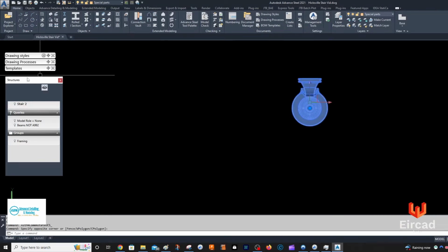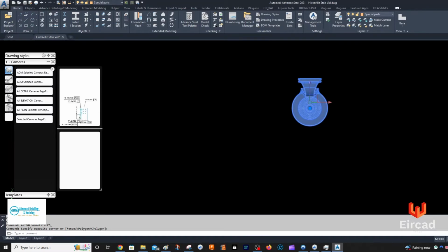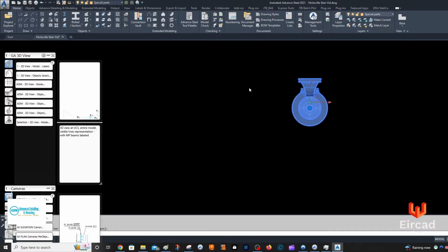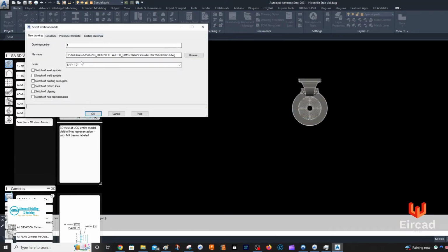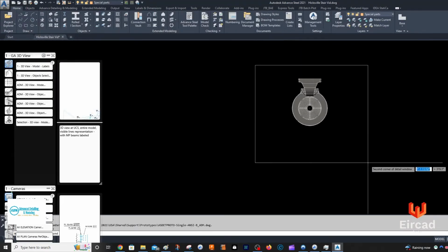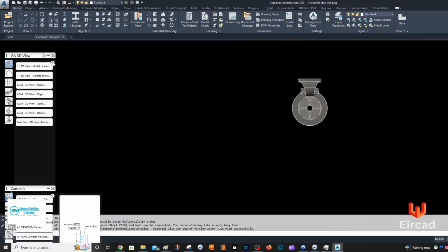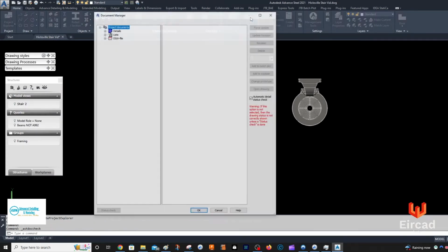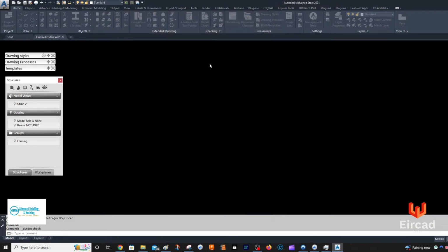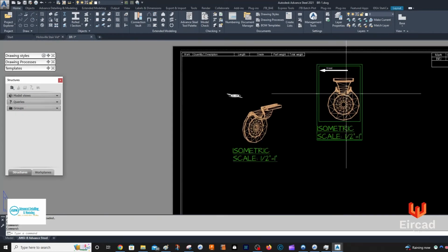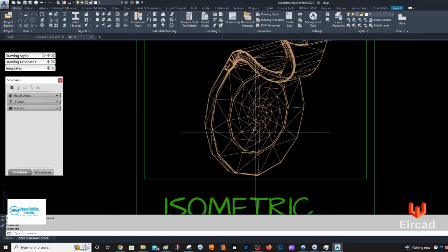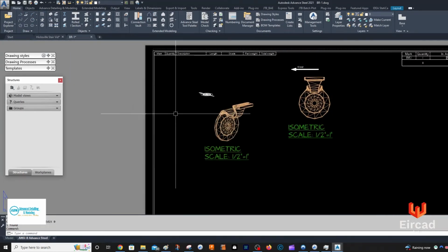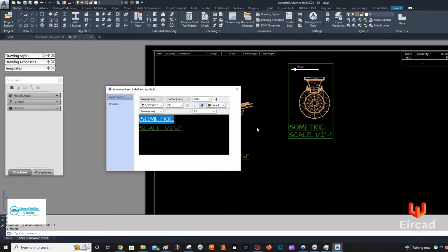And then select this again and the top one, go in here, modify the settings, half inches to 1, existing drawing, okay, and so on, right? So now let's put that on the drawing on the sheet, and document manager, let's open up that sheet, and there should be a second view there is. Now this is probably a poor example, right, with all these lines, but you'll get the idea. So then you'll want to change this to like front view, and then you can add dimensions, right?